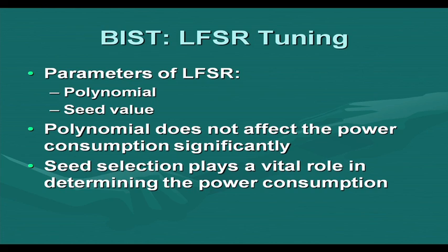The reason is very simple. If you look into the individual bits of an LFSR, if it is a maximum length LFSR, then all bits will have an equal number of transitions in them. So, in terms of circuit power, they often translate to the same power value. So, the polynomial does not affect the power consumption effectively, but seed selection plays a vital role.